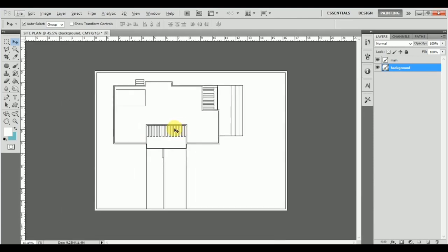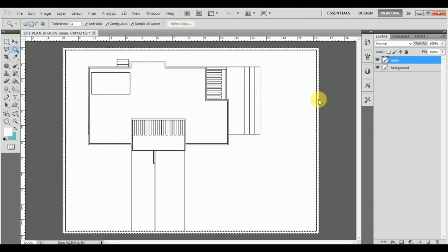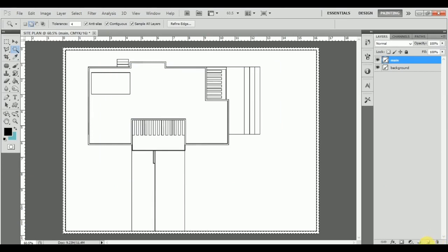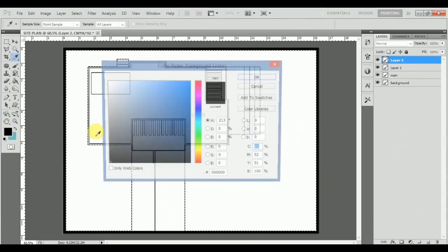Now guys, once we're done with this much, you can see over here that we have basically the entrance for the driveway, plus the walkway, we have the terrace, the pergolas, we can see the parapet wall, the stairs, and all of that. So we have to begin right from the bottom. So we'll start off with the walls over here on the side, which we will basically give as black color, which will be the boundary walls. So you can see I've created that first layer over here. Then we can go ahead starting from the grass, create a new layer, and we'll fill in light gray color.